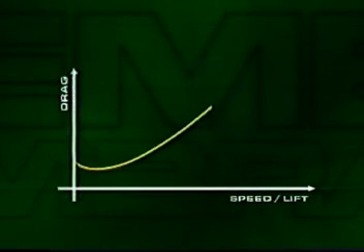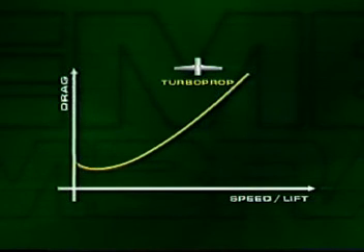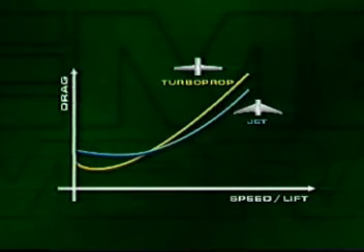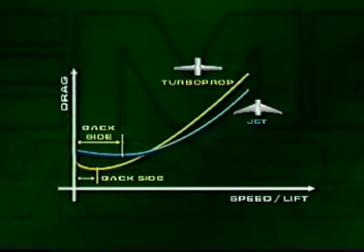This poor lift aerodynamic matter is also of high importance in the way in which drag and lift vary with speed. The following figure shows how the total drag varies, comparing both the turboprop and jet aircraft. This shows a reduction down to low speeds, and then an increase with further reduction in speed. There is a point identifiable as the minimum drag point, which is the mark to identify the backside of the curve. That is, in the low speed range on the backside, reducing the airspeed actually increases drag. Flight on the backside of the curve requires you to take care with airspeed, not allowing it to reduce.